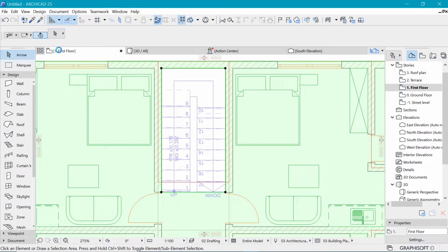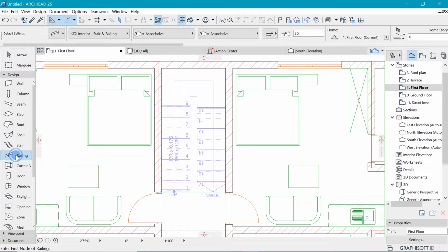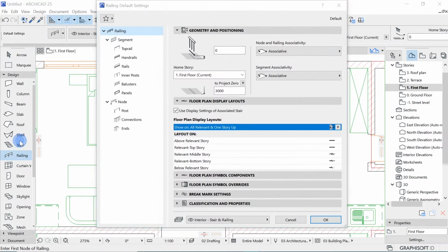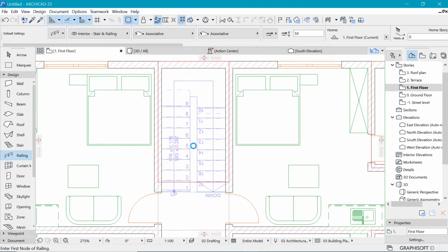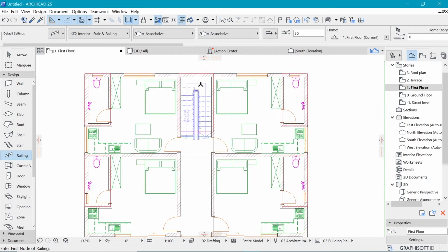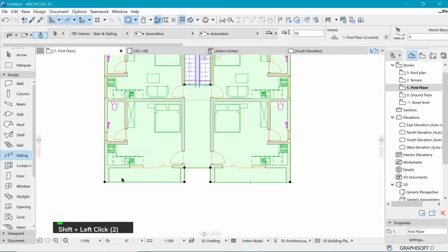All right, so the first kind of railing, we will just use the default rail. So let's say okay, and just hold down the space bar to click on this area. You can see it's going to be formed on the inside, and I'd like it to be formed on the other side. Okay, so we change that and make sure that it's formed on this other side along the staircase. Okay, that's okay.